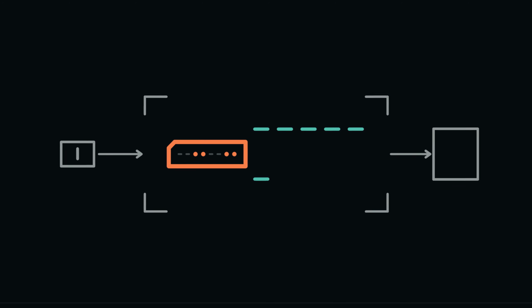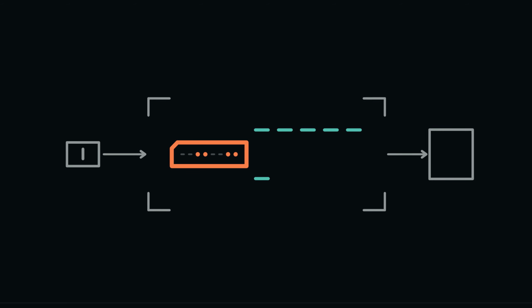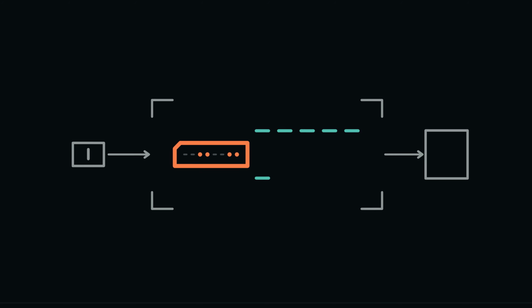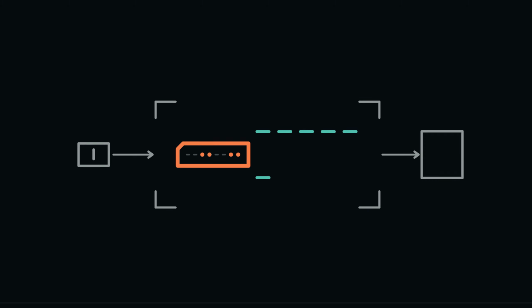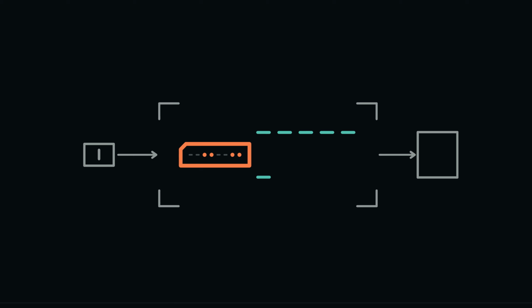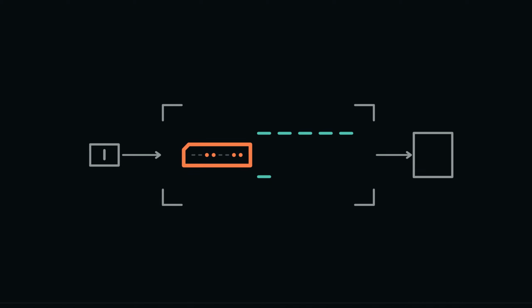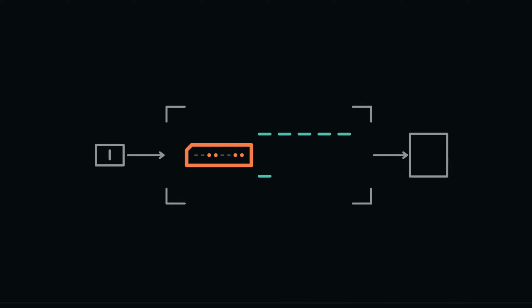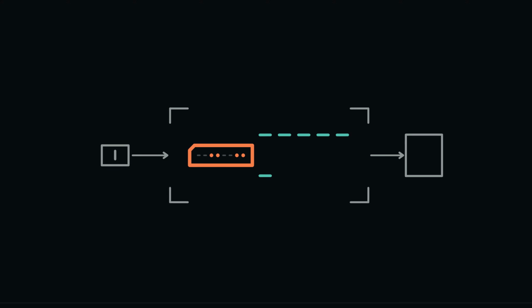An instruction is not a word that the processor understands as language. It is a bit pattern divided into fields by an instruction set architecture, or ISA. The ISA defines which patterns are legal and what architectural state transition each legal instruction must produce. It is like a form only in the narrow sense that position determines role. A number written in the address box is treated differently from the same number in the quantity box. The limit is that hardware does not read headings. Decoder logic responds to fixed bit positions and values.